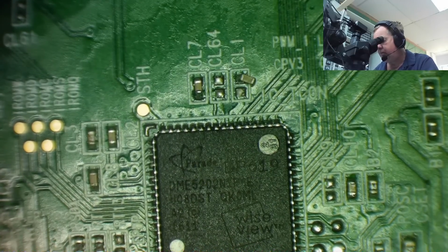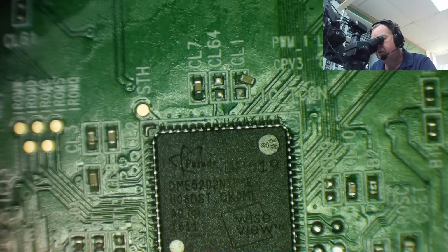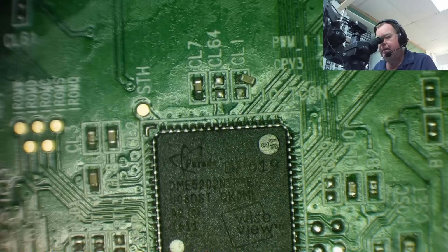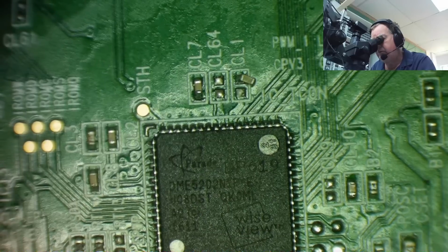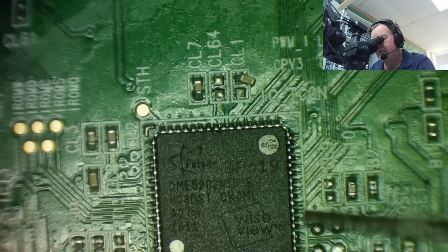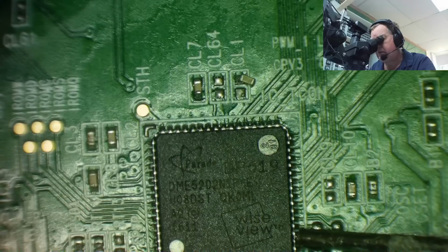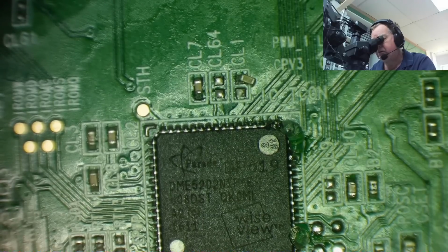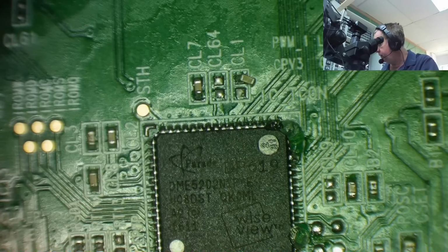Yeah, this certainly looks like a solder bridge just here, so we'll try and clean that up first. Get some flux on here. All the rest of this side looks good. There might be another bridge there as well. There might be one there and one up here. The rest of the side looks good. Okay,